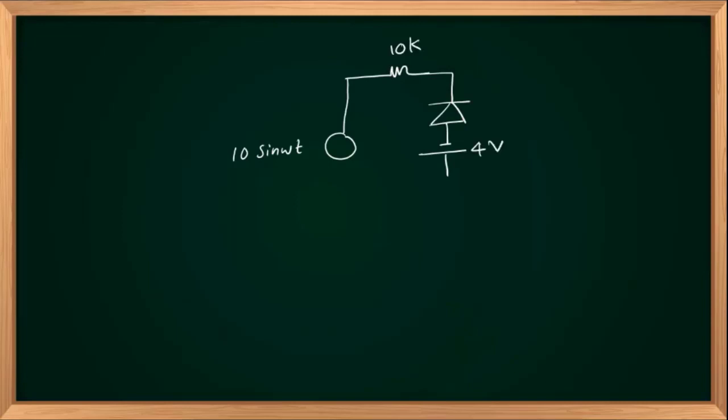Any other doubts? Let us get into the other problem in which we have a resistor connected in series with the diode. That kind of problem we didn't discuss in yesterday's class. So let us have another circuit. Input is as usual 10 sin omega t. You have a 10K resistance in series with the input source. You have two branches. One diode is connected towards up with a reverse bias of 4 volts. And there exists another 10K resistance here.